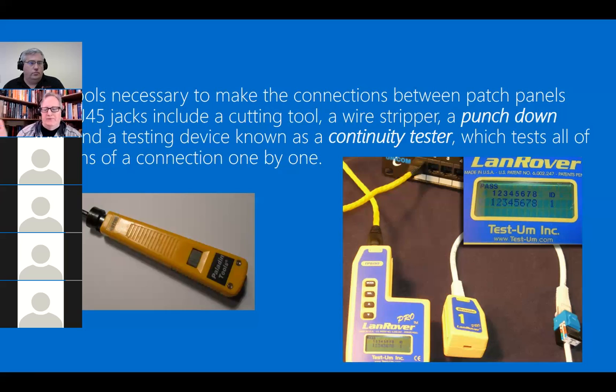So I absolutely, one year, bought cheap cabling where the twisted pair count was good, but the twists were so far apart that it had interference when you neared that 125-foot length, and you couldn't even use the cable. So it wasn't even really correctly rated for Cat 5. It wouldn't work. So in answer to the question about the difference between the categories, you're right. The connector is basically the same.